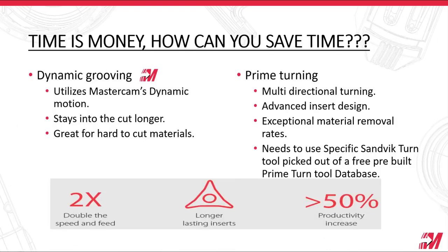And why do we want to use possibly dynamic grooving or PrimeTurning? Well, time is money, and how can you save time? These tool paths will save you some time. Dynamic grooving utilizes Mastercam's dynamic motion, so it rolls into the cut, rolls out of the cut, stays in the cut longer, and it's absolutely great for hard to cut materials.